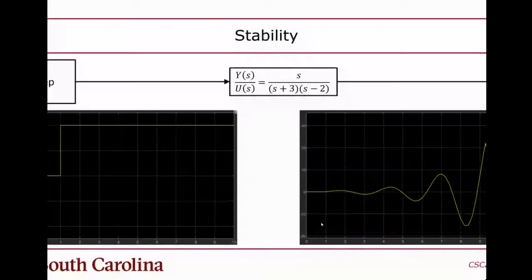Okay, so I mentioned that you can also simulate. If you go into MATLAB Simulink, you can simulate other inputs, not just the impulse response. You can also look at the step response too. I went ahead and did that because it's easy to do in Simulink. You literally just go into Simulink, drop down a source, and say I want a step source.